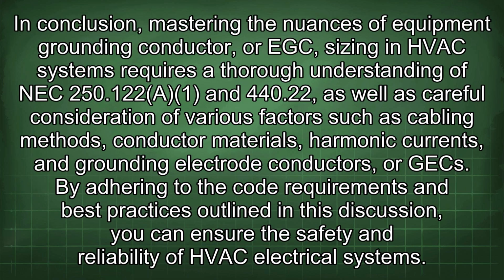In conclusion, mastering the nuances of equipment grounding conductor, or EGC, sizing in HVAC systems requires a thorough understanding of NEC 250.122(A) and 440.22, as well as careful consideration of various factors such as cabling methods, conductor materials, harmonic currents, and grounding electrode conductors, or GECs. By adhering to the code requirements and best practices outlined in this discussion, you can ensure the safety and reliability